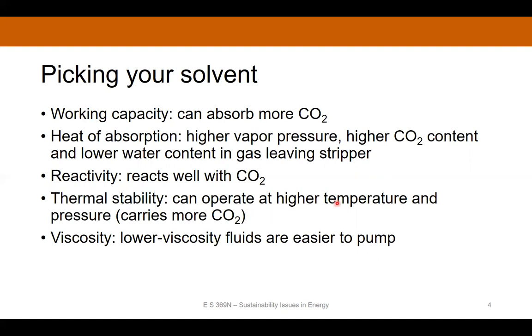So it has to be able to operate at high temperature, and the higher the pressure we can operate at, the better, because then this will allow the solvent to carry more CO2. And lastly, we want to have a lower viscosity, because that makes it easier to pump. You have fewer frictional losses, and the pump efficiency is improved as well.